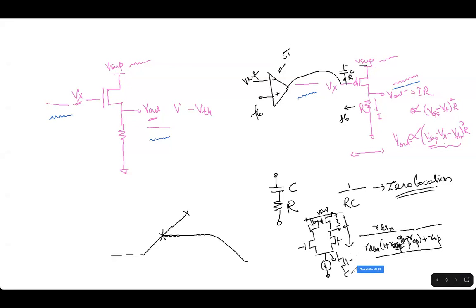The tail is also an NMOS, not an ideal current source. So two NMOSes below, one PMOS. So what is near to the supply? Of course, the output point is near to the supply. Below, towards the ground, there are two transistors. Towards the supply, there is only one transistor. Hence, you may assume that there will be some contribution, some part of the VSUP, available at the output node of the 5T OTA.